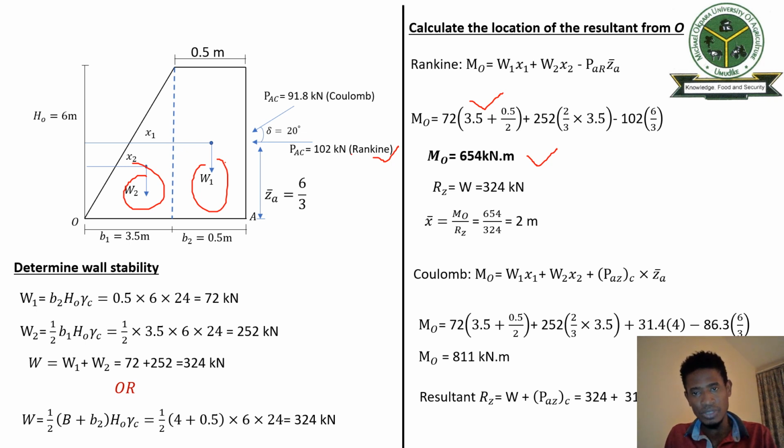Now, the next one you will have is this value here, which stands for the value of the vertical force or the load, that is R. So if I now want to find the resultant, where the moment is acting, the resultant of the force in this particular stuff, you remember that when you divide the moment by the force, you will get the distance.